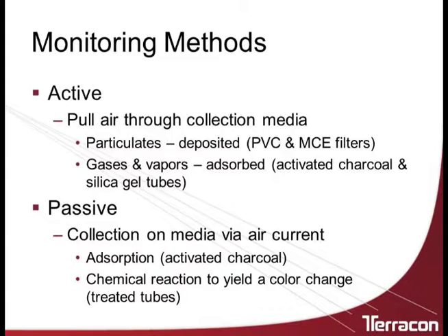If they're gases and vapors, typically they would be adsorbed as that air moves through the media. They would be adsorbed onto activated charcoal or silicate gel tubes or Tenax. There are a host of collection media for gases and vapors dependent on the specific type of material.